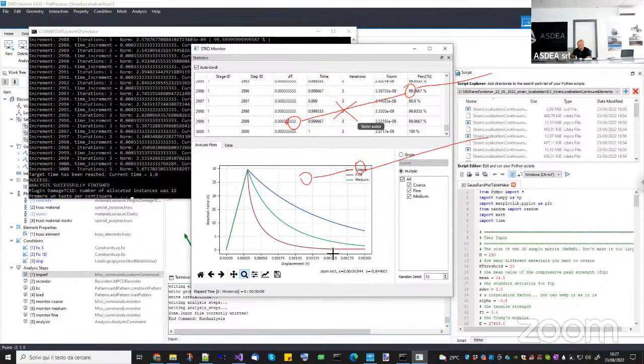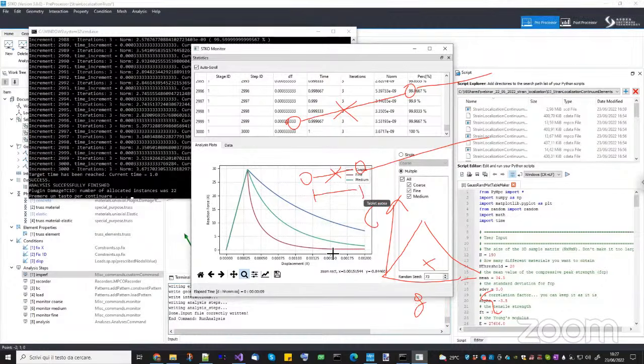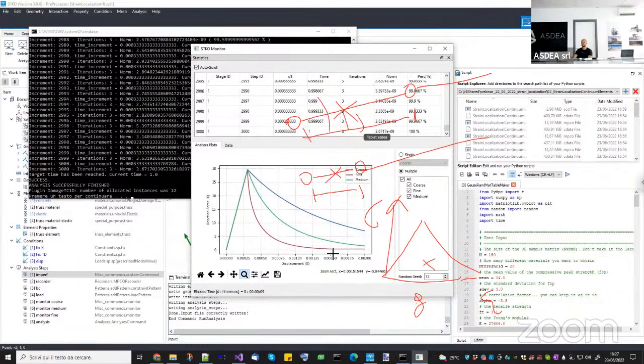This one is failing, but also this one. So they have the same stress strain law, the same sigma epsilon. So this one is the specific fracture energy. This one will be integrated over this length and over this length. So it is clear that the coarser mesh will dissipate more energy because we have the same specific energy for a larger volume.